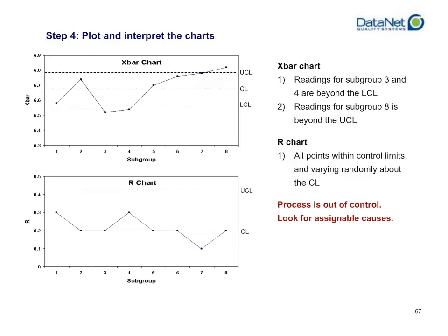These control limits came from your data. You calculated these control limits. It's actually based on the actual voice of your process. And since it is out of control, it's actually showing that there is something that is statistically significant that you're going to want to investigate.